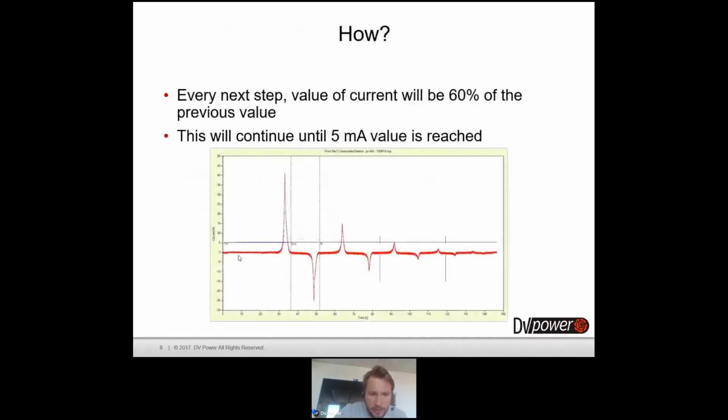This is one demagnetization process recorded with our device. As I told you, we use DC current and voltage, and this current is charged to some value, then it goes in the opposite way. So we change polarity, and again change polarity, and in each step we decrease the value of this current.